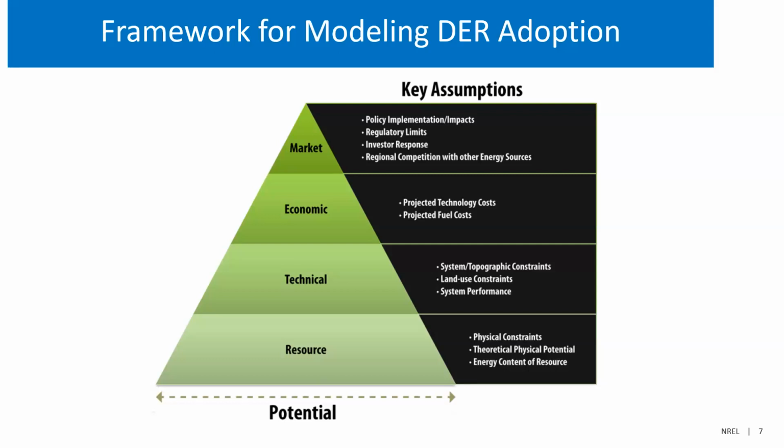You can think about it as a bigger pie, and the pie keeps decreasing as we move up the pyramid. Then we move into the technical aspects: I'm located here, but what kind of building is it? Is there shading? Is there a tree nearby? What is the tilt and azimuth of my roof? How much PV capacity can my rooftop technically provide?